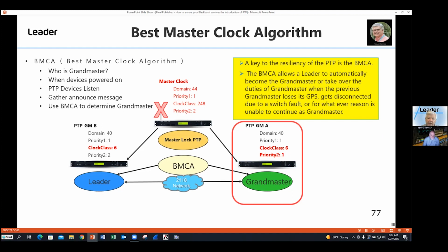If you look at the domains, it's a different domain feeding the two units down below, and then their output will be on the domain that will be your truck's domain. The domain out of the first one is just the domain to lock the two units, and it's not part of that BMCA polling, but it just gives the same stable clock to both units so that it's the equivalent of GPS lock from the BMCA. It will work between the two units as expected.